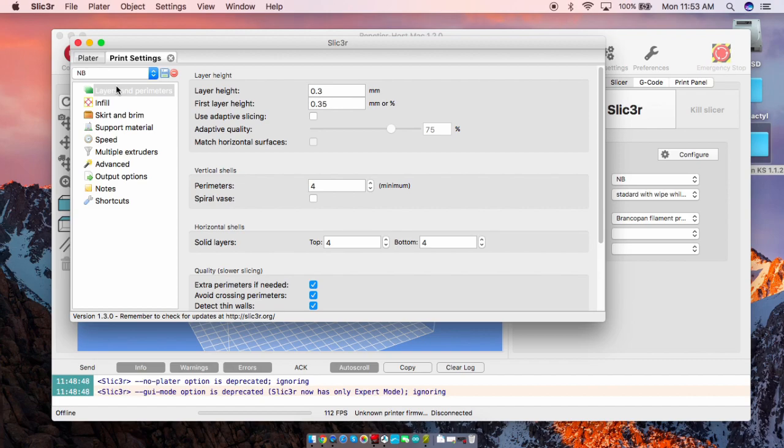You might think, if you're new to 3D printing, that you would want to print everything with 100% infill and just fill the thing up. But that leads to its own problems, because the filament expands and contracts as it's being heated and cooled. If you print everything at 100% infill, you'll have some dimensional accuracy problems and curling. And there's also smarter ways that you can create a super strong part by just putting the filament in the right place.